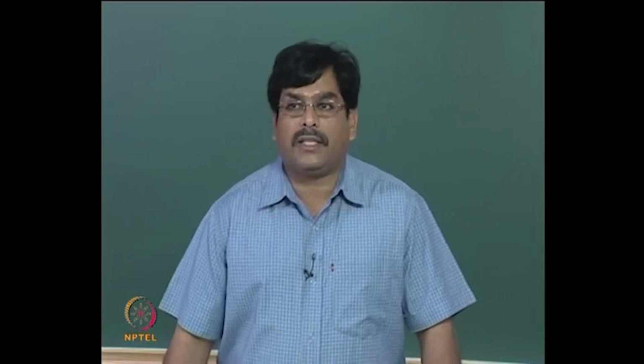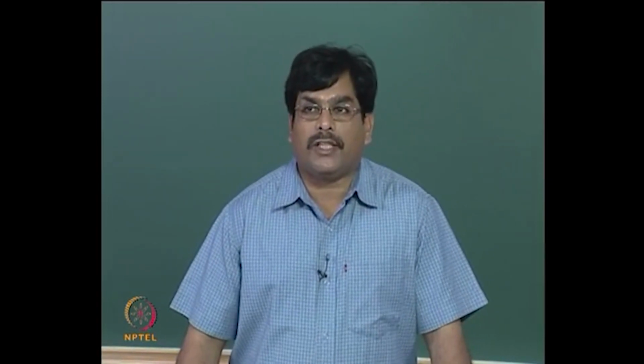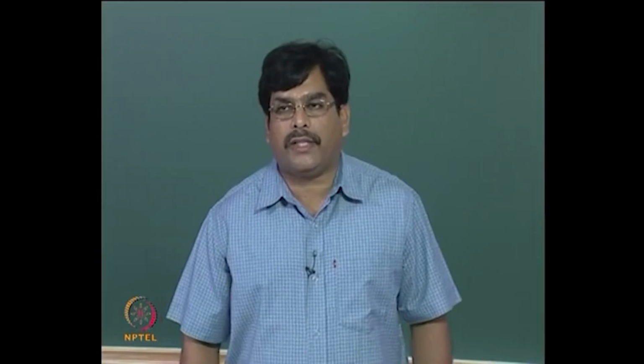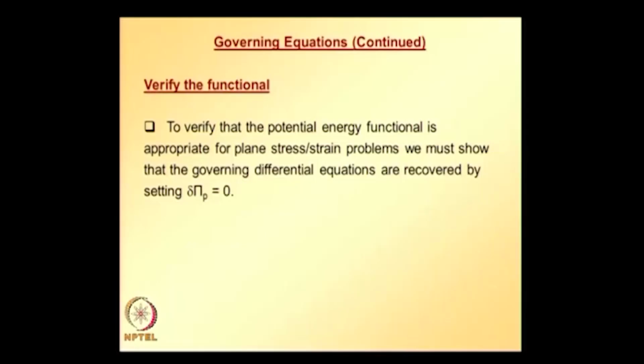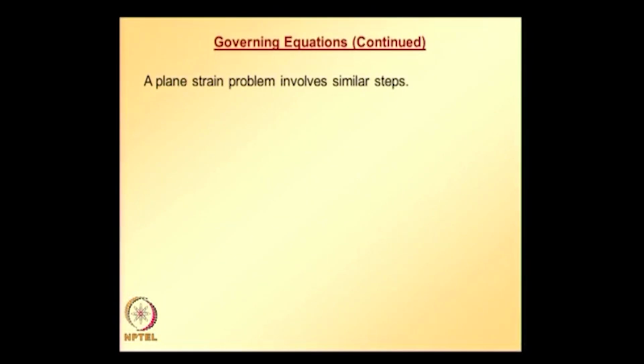So, Pi is defined as U minus W. We need to take the variation of it, and finally, we need to see whether we can recover the governing differential equations corresponding to the 2D elastic problems in terms of displacement. So, that is how we need to do it. Let us proceed, and let us assume that the problem is a plane strain problem,